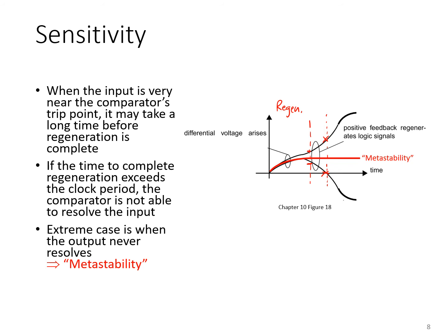But another way that's perhaps more practical is, if you have an RS latch here, then really what you care about is have these voltage levels at the output of the dynamic comparator gotten large enough to trip the output of the RS latch. So you can just look at these output voltages here.